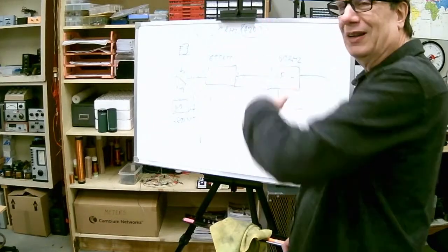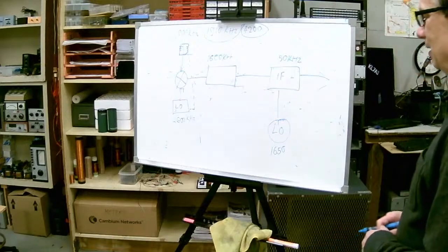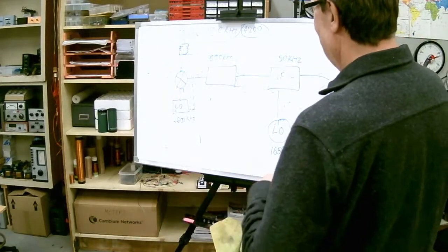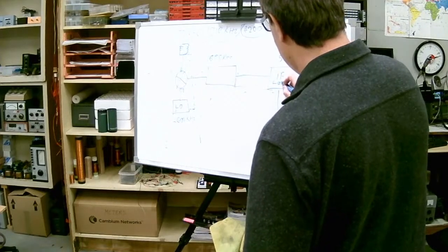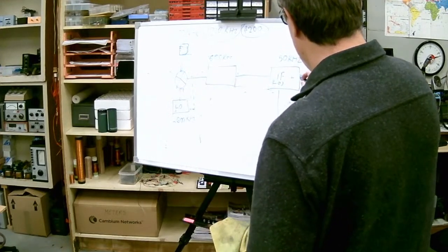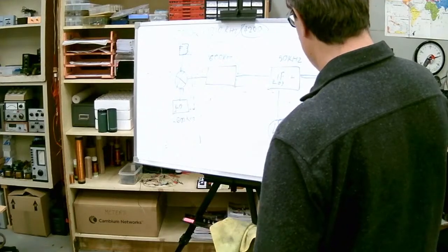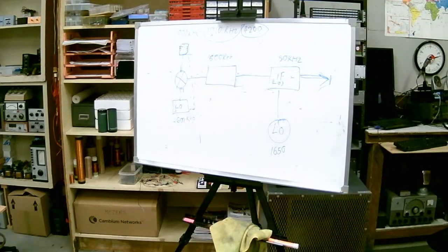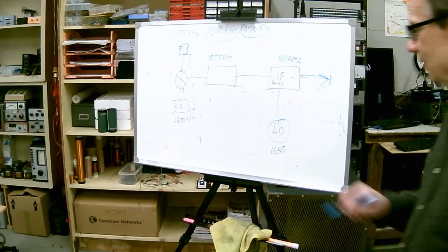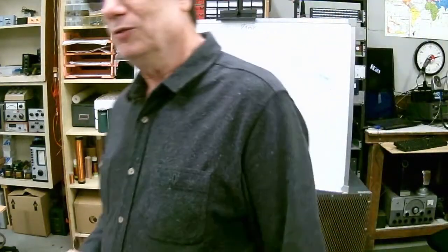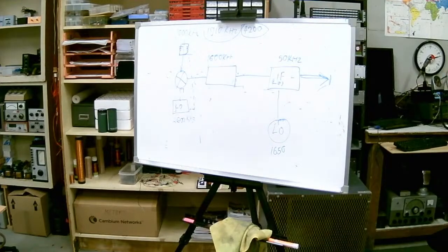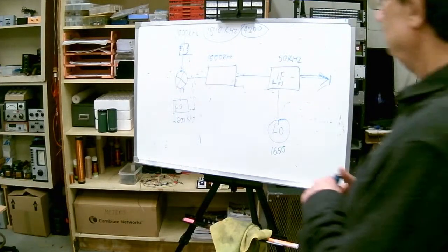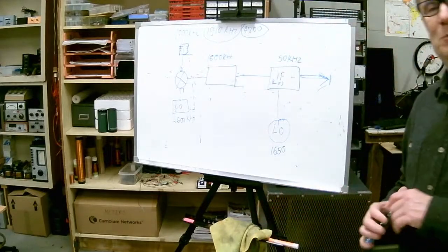Okay, you're just getting one frequency. There's no possibility of that. So it's the low IF. Interesting. And then here, this would go to your final detector. And lo and behold. Okay. So that's a dual conversion receiver, which is just about everything I got here, a dual conversion receiver. So that's the evolution of communications receivers.